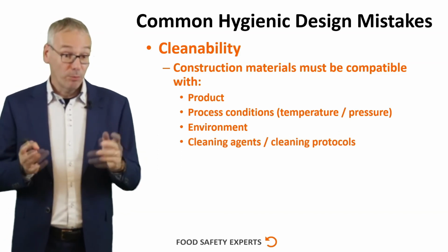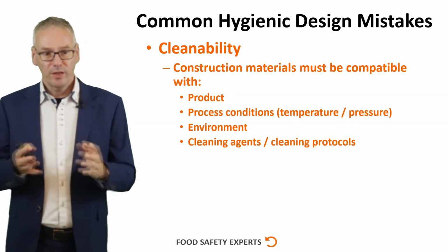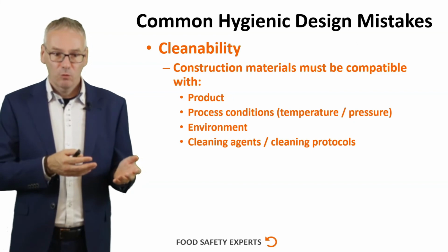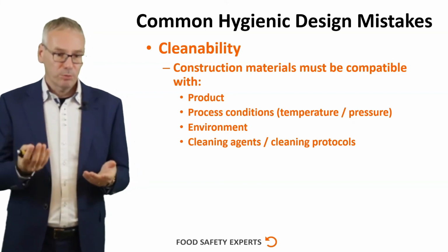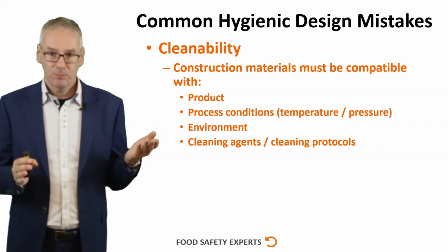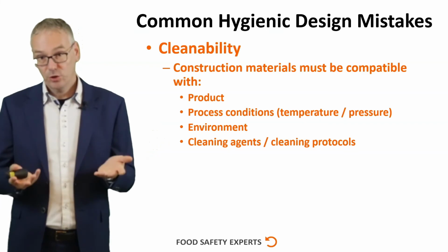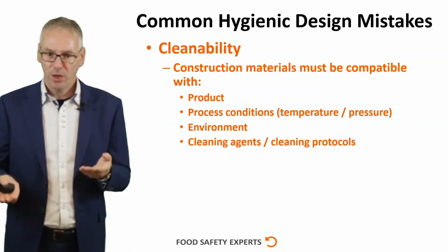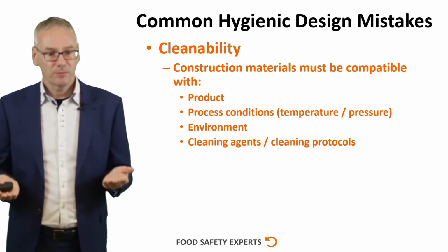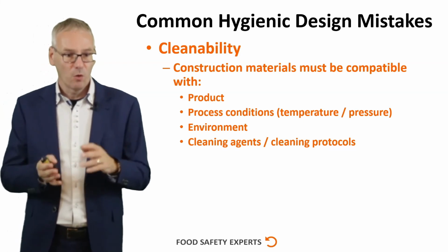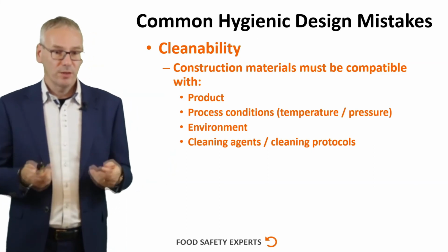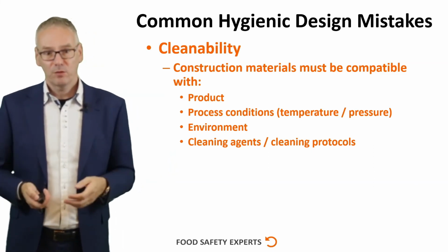And also a very important aspect to consider is the type of cleaning agents that you will need to clean your product and the cleaning protocols. For example, if you have a product which is fatty, you will typically use alkaline cleaners to get rid of the fat. But if you have a product which results in the deposition of limescale, then from time to time you will have to use an acidic cleaner. And not all types of stainless steel go very well with acid cleaning agents. So you really need to consider what the cleaning application is and the type of material that you're going to use.